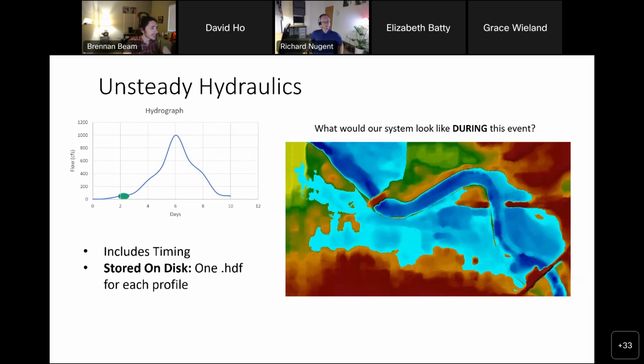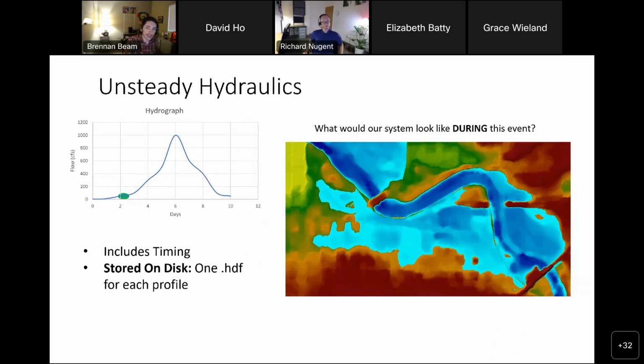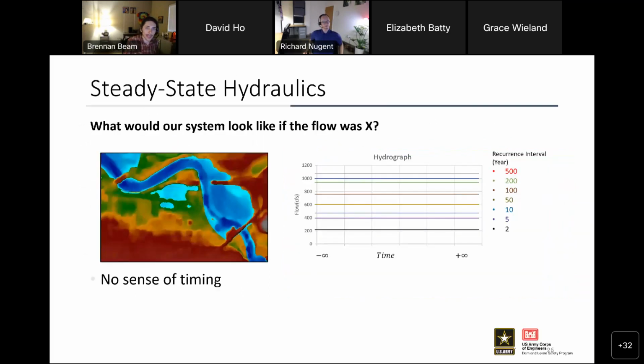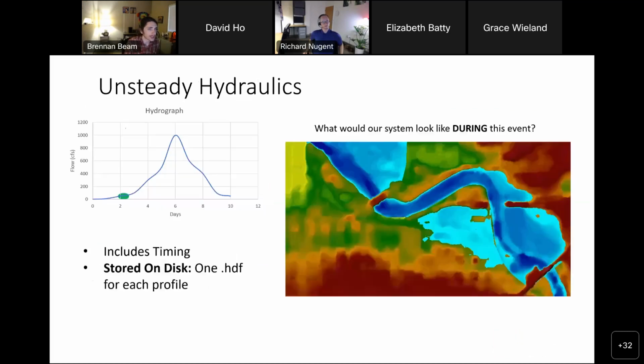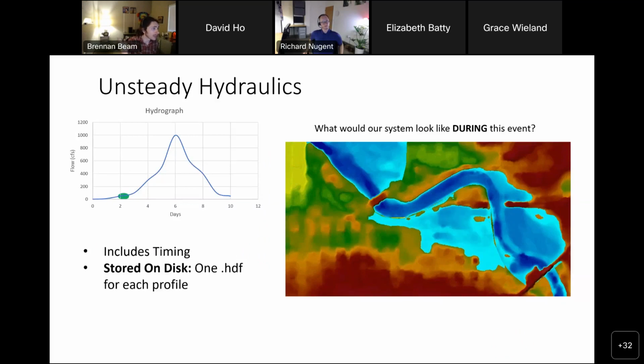You can see I'm simulating the same area as I was in the last, but in this one, you're seeing water actually pour over that levee and move through the system. Whereas if I jump back, as this clicks through, water is just jumping places. This is a much coarser approximation of the solution. This is a lot more detailed way of modeling something. This is especially important when you have leveed areas that are going to potentially fill up with water.